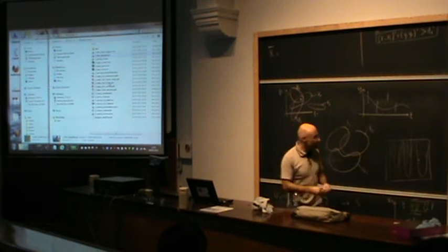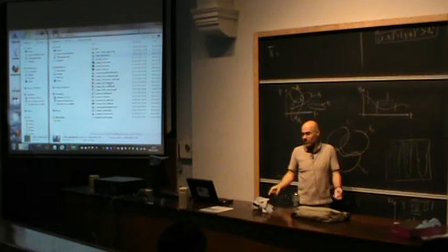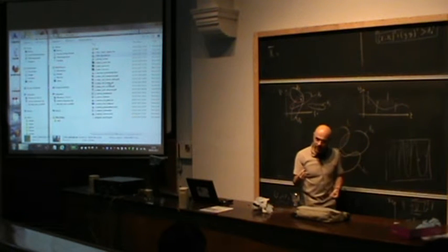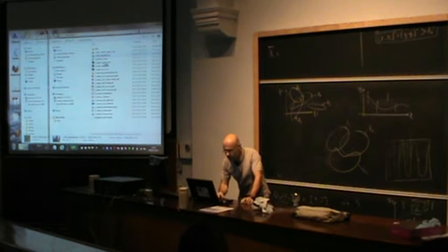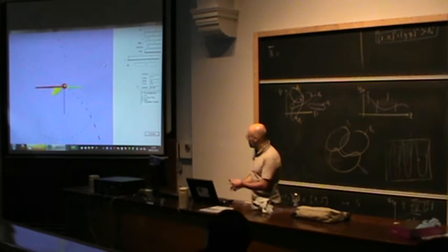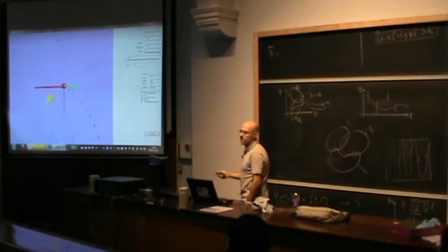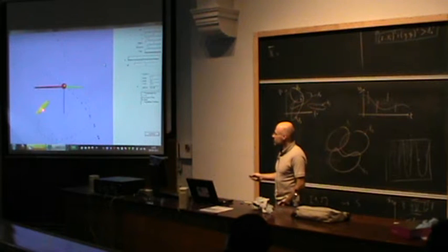And it is not possible for the robot to surface every 10 minutes to localize itself. So we can put better and better sensors, but it costs a lot of money, and that's why we want to avoid that. So first of all, about the control. Control algorithm for this, as you can see here, the target, submarines, we use some kind of feedback linearization method that normally gives a convergence of the robot toward the target.